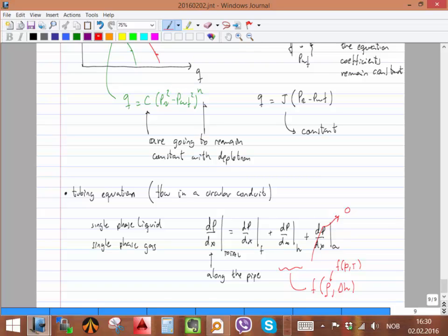And then you have the friction pressure loss that is affected by the velocity, or in a more general way, by the Reynolds number, that is density, velocity, viscosity, and diameter. So if I have a very viscous fluid, I will have more losses than if I have a less viscous fluid. And if I have a high velocity, then I will have more losses than if I have lower velocities. I'm not going to go into all the details of that, but just keep the idea.